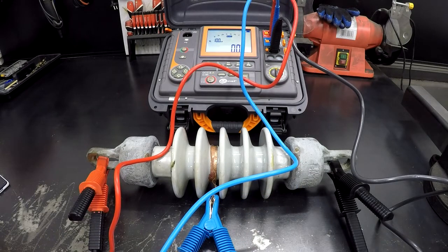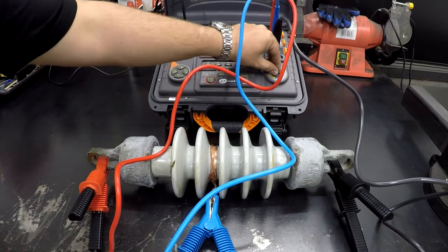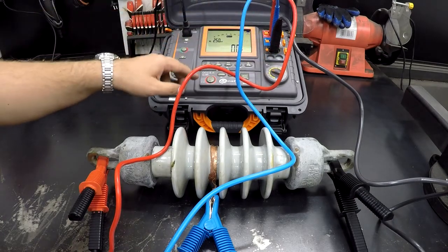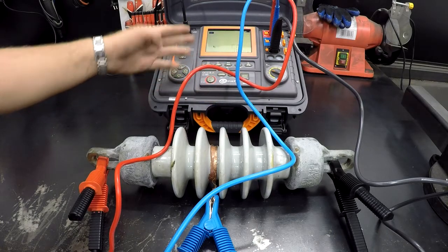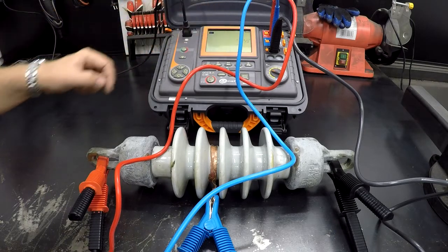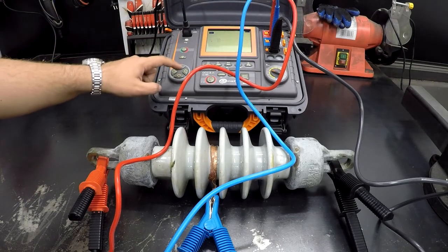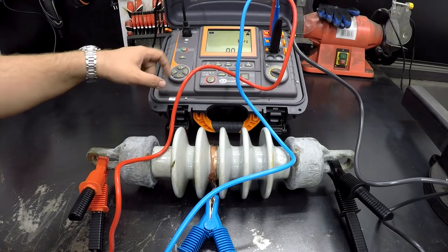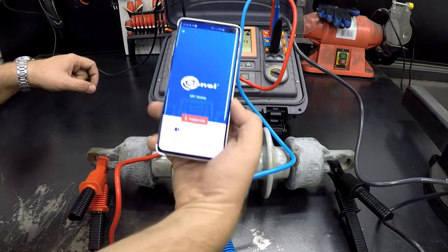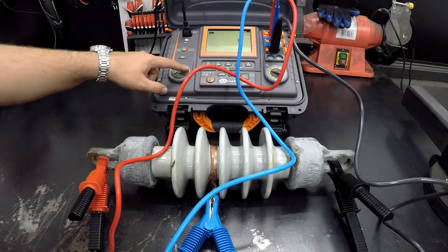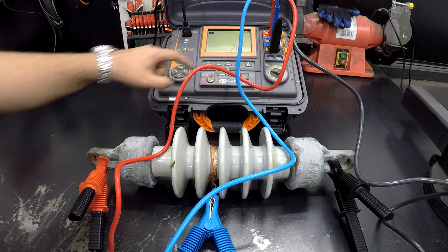For this presentation, I choose any test voltage and set times for calculating the coefficients. So as not to extend the movie, I just set short times: T1 20, T2 40 and T3 50 seconds, and the total measurement time 55 seconds. Measurement current, for example, 7 milliamps, and I turn on the remote control via Bluetooth, and turn on the SR.